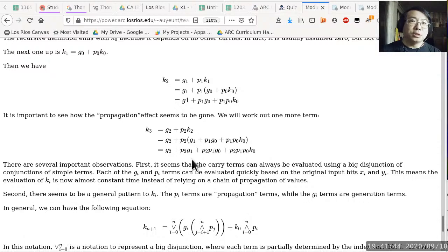This is also the version where we can parallelize the most to get the best speed out of the circuit. That is why we expand everything out, so that we can have parallel circuits doing computations at exactly the same time. So I'm hoping that nobody used this definition and then tried to connect K2 into the circuit of K3, because that would be considered an incorrect answer.